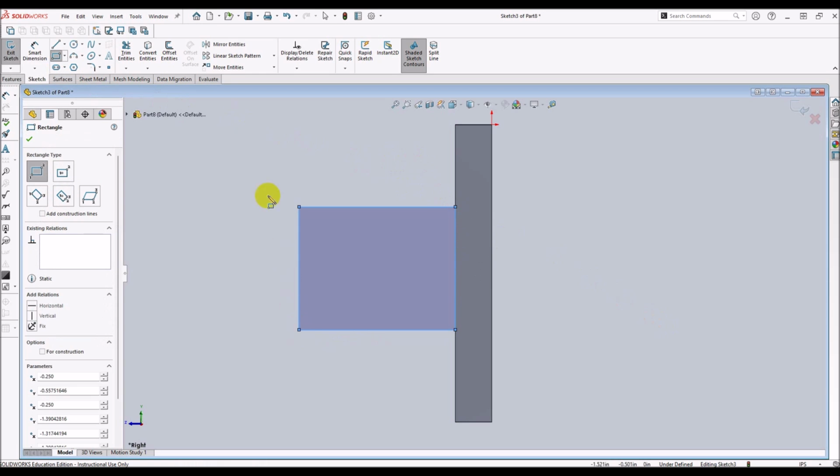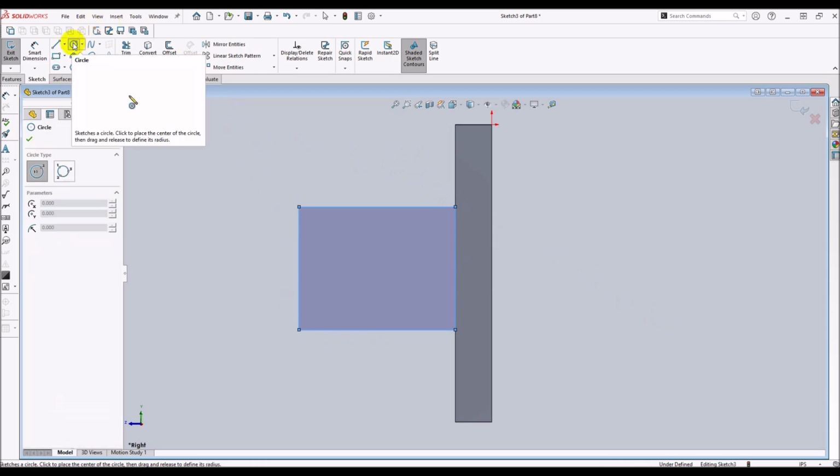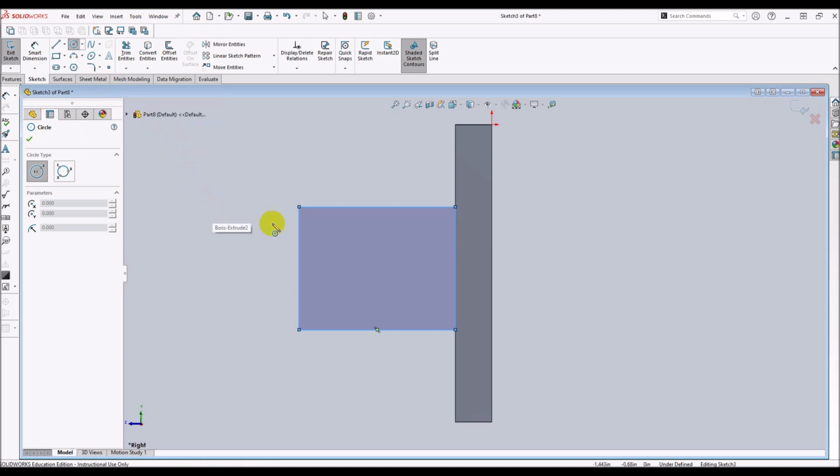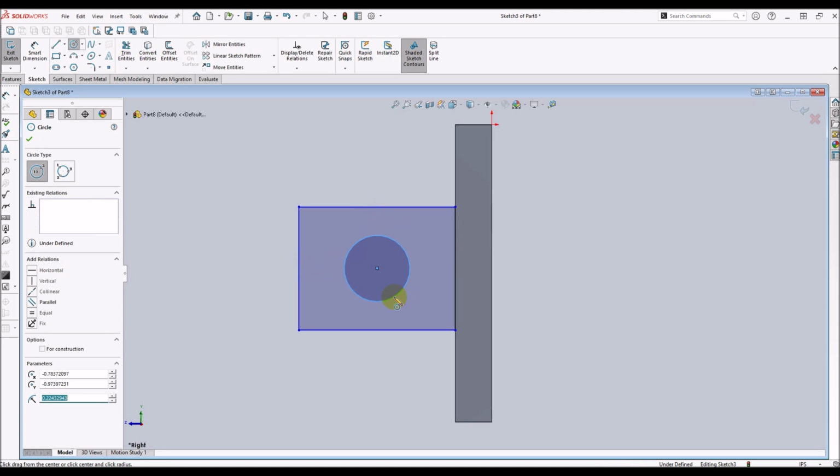We then select the circle tool as shown. This is when some of the automatic features become useful. What you'll see is that if we briefly hover over a feature, such as the edge or a center point, SOLIDWORKS remembers this and helps you align to that spot when drawing a new feature. Now that the circle is drawn, we can exit the sketch, and once again we see the Boss Extrude panel.